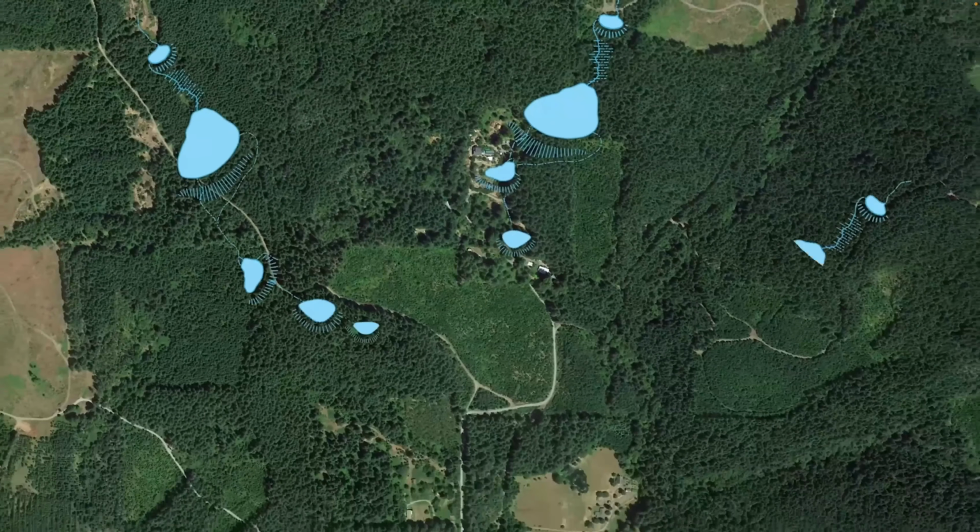Once we know where our pond site is, the next step is to generate cross-sectional and overhead view diagrams of the pond. We can look at how much soil we can expect to move. We can look at what is the total area that's going to be impacted, how many trees need to be removed, etc. We can start to perceive what some of the impacts will be on side slopes and things like that as we excavate to make sure that we're maintaining the proper inside slopes.